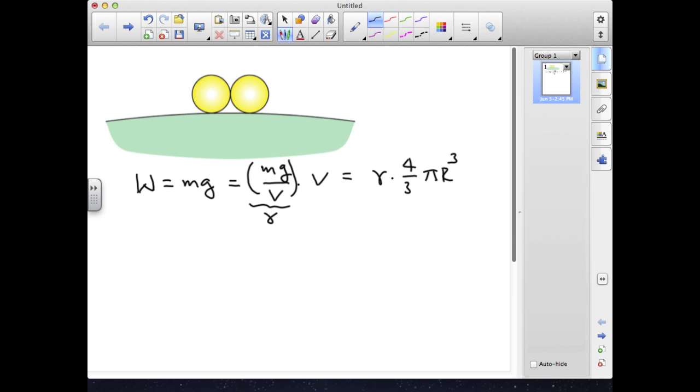Now, because we have mixed units, we're going to have to convert one of these to the same units as the other, and I will choose to convert SI units to English units to start with respect to the radius. So the radius is 50 millimeters. Right, that is 50 times 10 to the minus third meters times 1 foot per 0.3048 meters, and that gives me a radius of 0.164 feet.